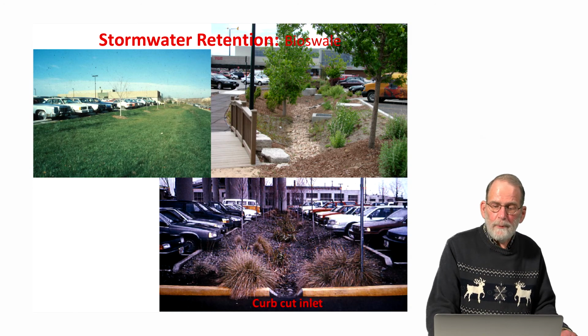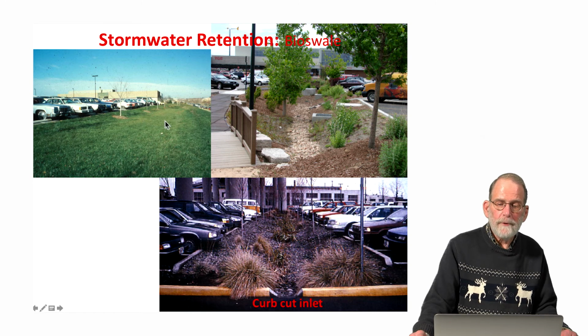Here we see some examples, other parking lot details where again we have an open swale system that's filled with gravel. So the open swale, gravel-filled swale captures water coming off of the parking lot and infiltrates it. We see examples here where there's a bioswale that contains gravel.